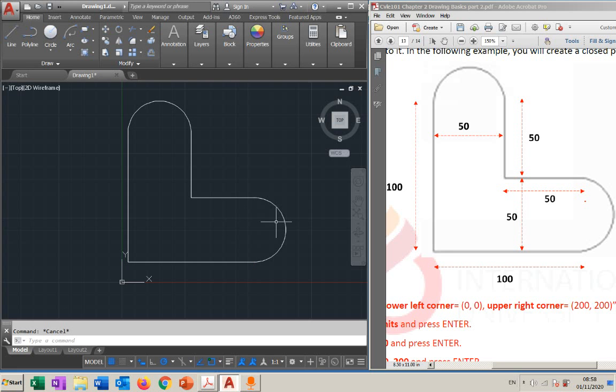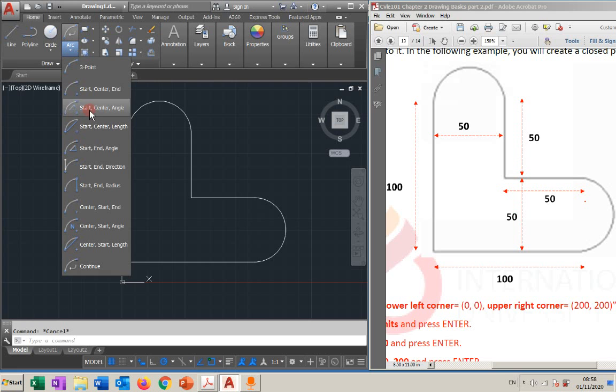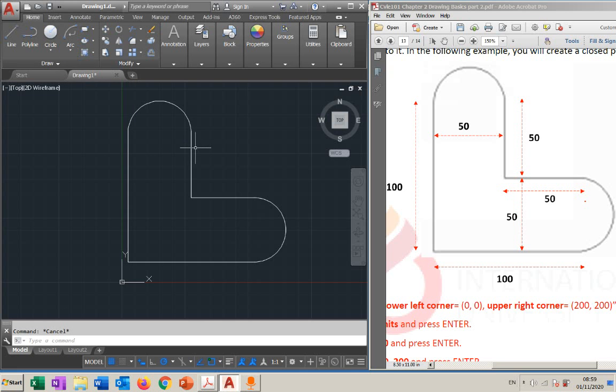This is how we use Polyline in AutoCAD. So it's a combination of line and arc. You can use similar things that you know from arc, from line. So I need you to practice the things that you draw with line. Try them with Polyline, to see how they come out, at least to understand how to use Polyline. Remember, nothing new. It is still using the method of line and the options for arc. Some of the options, not all of them, for arc can be used within Polyline to draw the object.